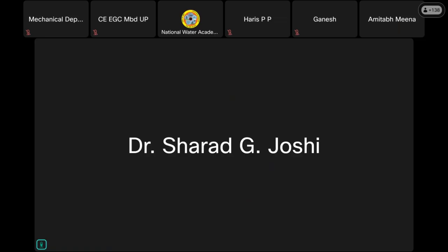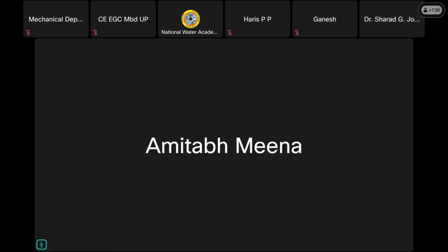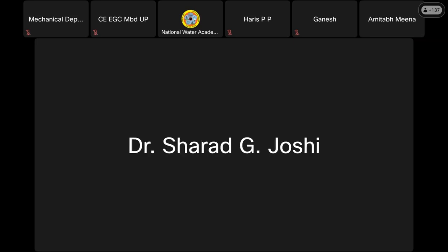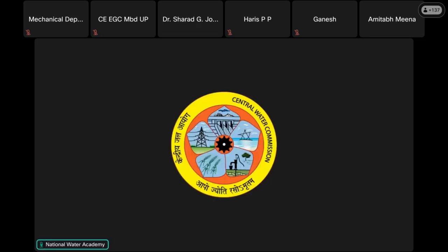You can send a diver with a ribbon, and he explores the surface of the dam with a grid identified. Wherever the suction point is, he will notify the person sitting above with a video, and note the chainage and depth. So it is about suction for leakage, where the water is entering into the dam body. Yes, that is the meaning of suction point. Thank you, Joshi Sahab. Now, please move to the next question, Amitabhji.